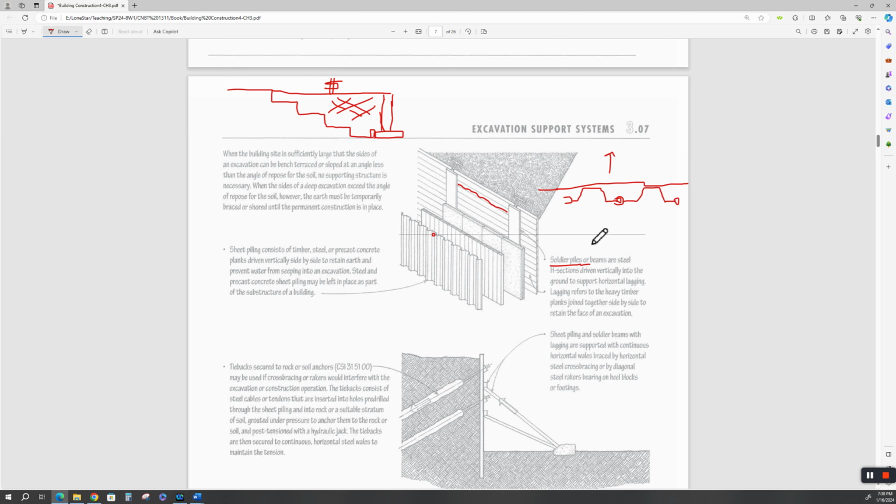They'll excavate out this side. They'll come in and pressure wash all the dirt away. And then if they're going to put a foundation wall, they'll form up one half of the wall. This would be the forming, and this would be the reinforcing steel. And they would just pour the concrete in here, and that would be the reinforced retaining wall or the foundation wall.